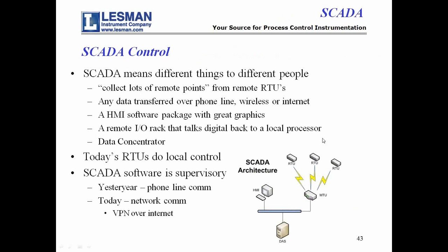So I'm going to use it sort of like the little diagram on the right here where you get a bunch of RTUs out there and then they report into a basic MTU and then you get that data into your SCADA software or your HMI software. SCADA software is typically supervisory because you're sending out control information over a control link to a remote spot.